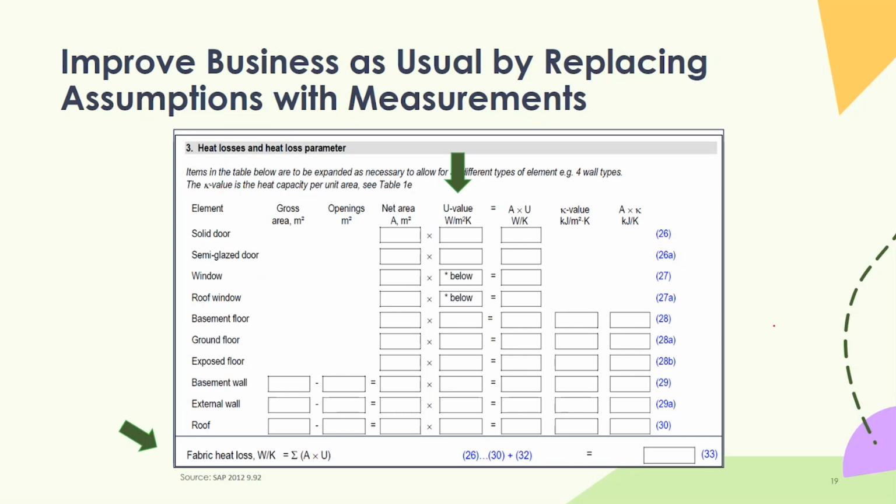And once you have an accurate model, an accurate understanding of the building fabric, everything else flows much more readily from there. By knowing the fabric, you now know the peak heat demand that a heating system needs to meet. So then you can size heating systems more reliably, particularly important when you think of heat pumps and the fact that they need to be in the ideal operating window to be most efficient. It's going to inform your ventilation strategies, so how airtight is the building and therefore what ventilation system is going to be most appropriate. And with a good, robust model and understanding of the building fabric, you can then model behavioral aspects with more confidence because the fabric is a known quantity.